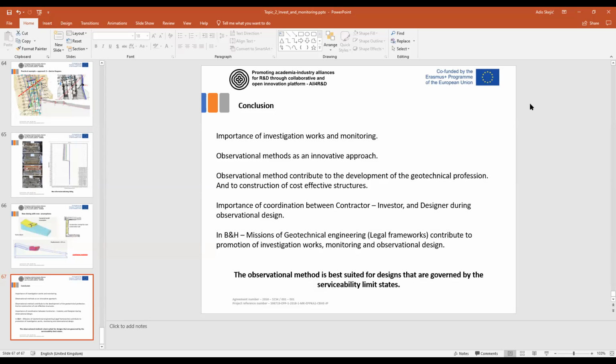No, my question was just, for example, 50 kilometers, because that's a long distance. So if there's going to be one every 200 meters, that means there are going to be a big number of boreholes. Why not? Actually, along the alignment. My experience is this number is actually not enough.